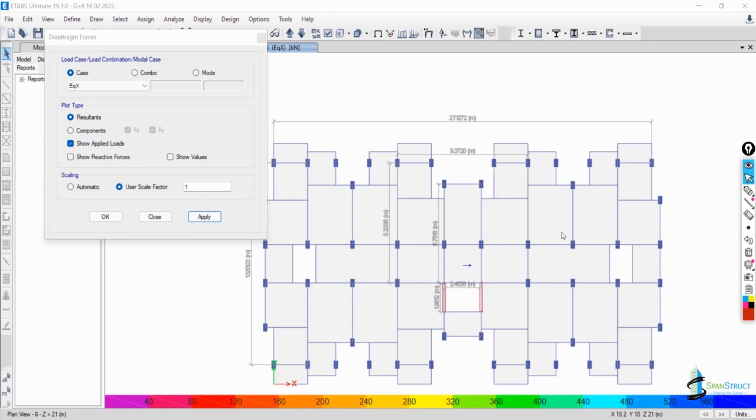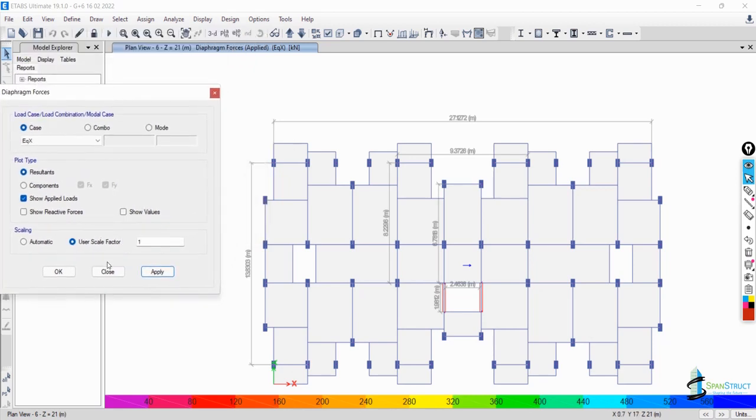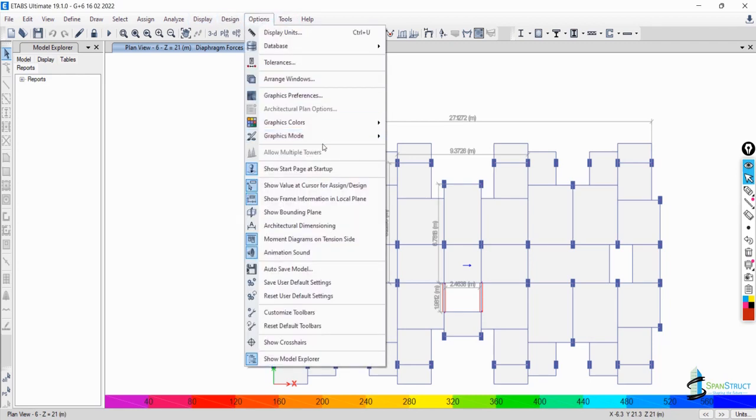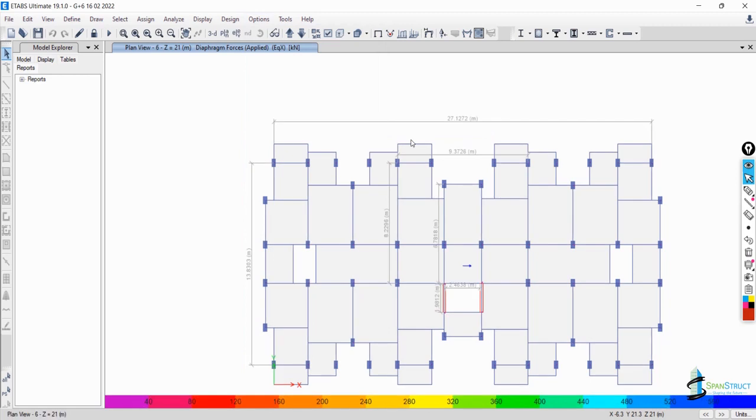What you can do now is switch this graphics to the standard mode, then the result you are looking at will be visible more easily. So you close this, go to the option here and find the graphics mode. By default the graphics is DirectX; you change this to standard graphics. Then when you place the cursor, you will find it shows force 593.135 with angle 0 here.